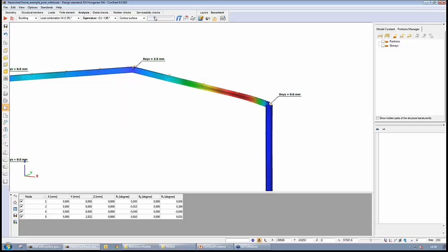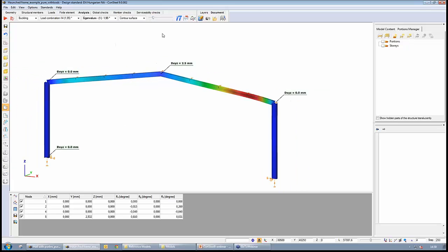Now the buckling is some kind of one wave buckling of the bottom compressed flange, which is completely unrestrained at the moment, and here the very high peak bending moment produces quite large compression at the bottom flange, and it can move unrestrictedly. And what is very important, due to this new situation, the elastic critical load factor